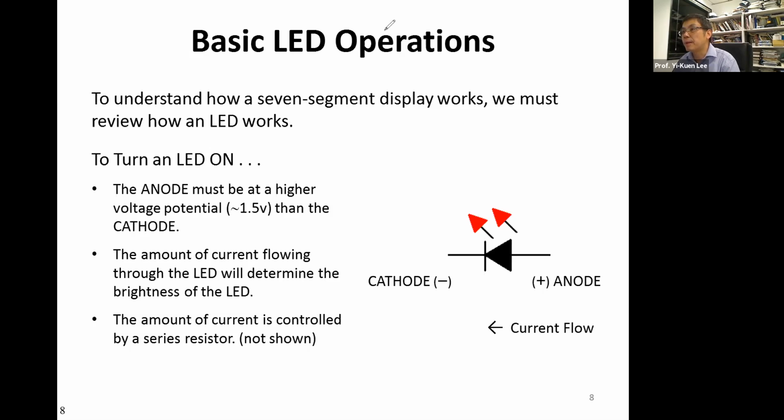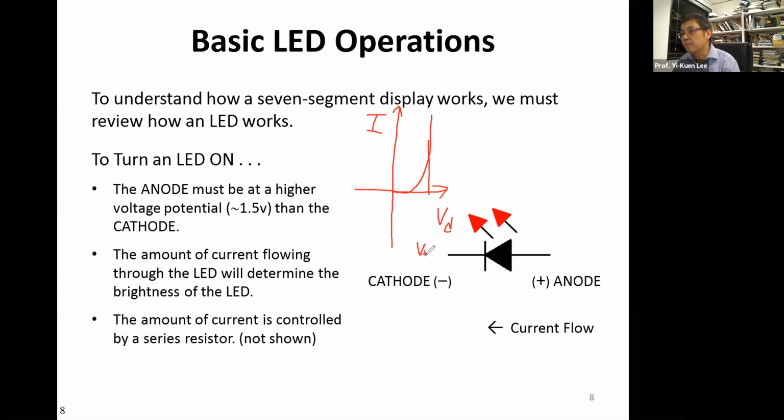Typically, we have seen the typical behavior of an LED. For the typical LED, X is V_D and Y is the current through the LED. So in general, we have this kind of nonlinear behavior. If we apply a voltage, for example 5 volt, to this kind of LED, what happens? Very possibly, if the voltage is much bigger than the threshold voltage, V_T, then you turn on the LED. But if your voltage is too high, what happens? What do you think? If the voltage is high, you can see this is an exponential function, and actually it's very possible it may burn your LED.